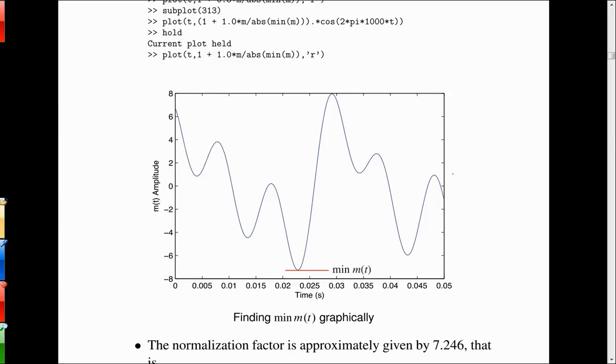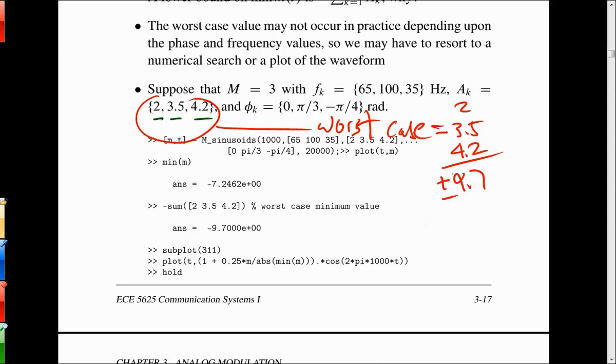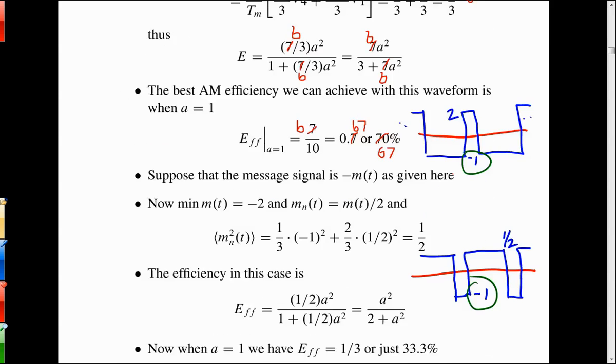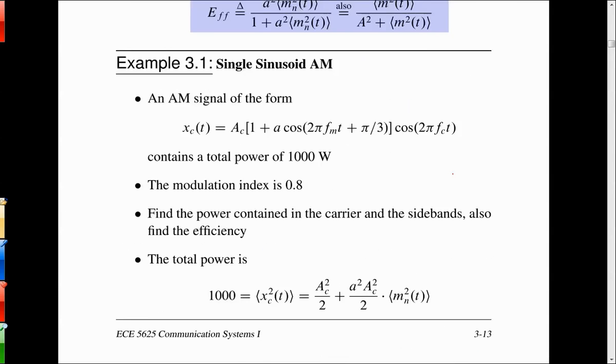In a radio receiver, you actually have another amplifier on the RF signal that comes into it called the automatic gain control, and it does the same thing, but it's on the receiving side rather than on the transmitting side, and that's to try to make sure that the signal into the envelope detector is about constant. Remember this?